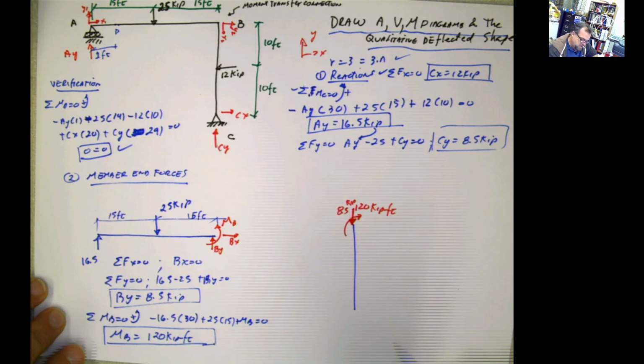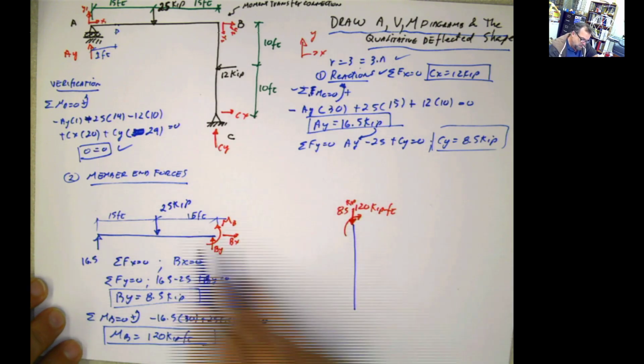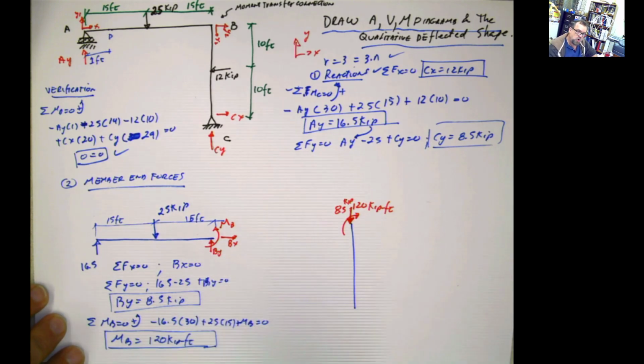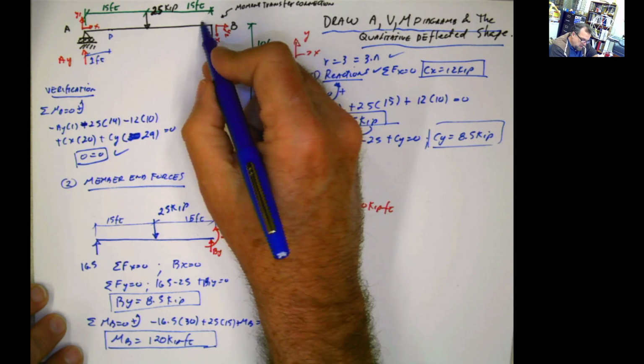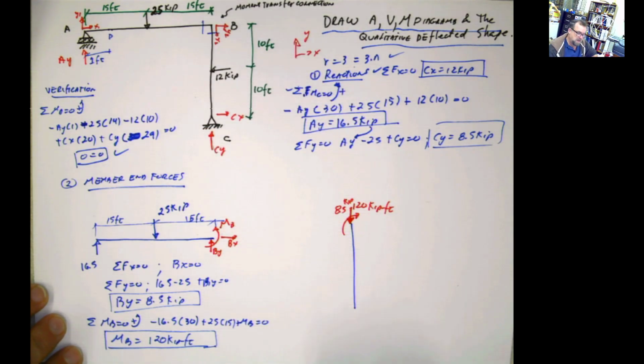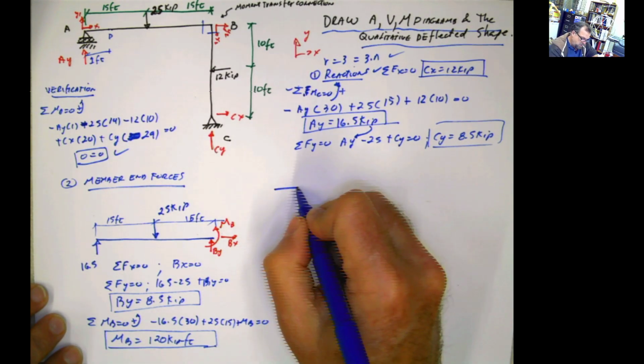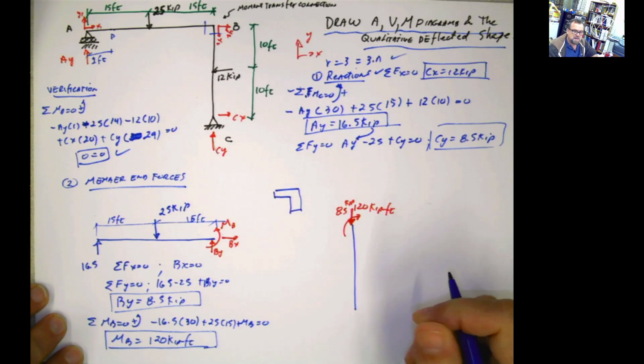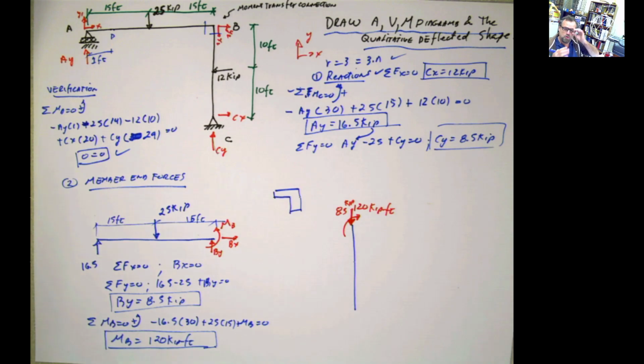So the transmission of the load is not member to member. That doesn't happen like that. It's member to joint and joint to member. So here you have a joint in this part. And that joint, if you draw it, it's going to look something like this. Exaggerating, right? And that joint can be, I don't know, the two members bolted together, welded together.